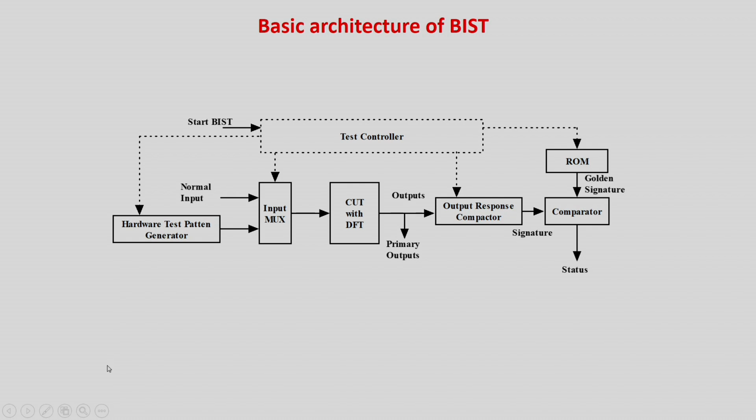So in whatever test patterns you have generated, assume that we will put it in a memory and put it into the chip. And same thing, we will also have a golden response comparator which is happening in the ATE, can also be put on chip. So we are making a miniature ATE and putting it on chip. That is actually called the built-in self-test mechanism. This is the pictorial diagram.